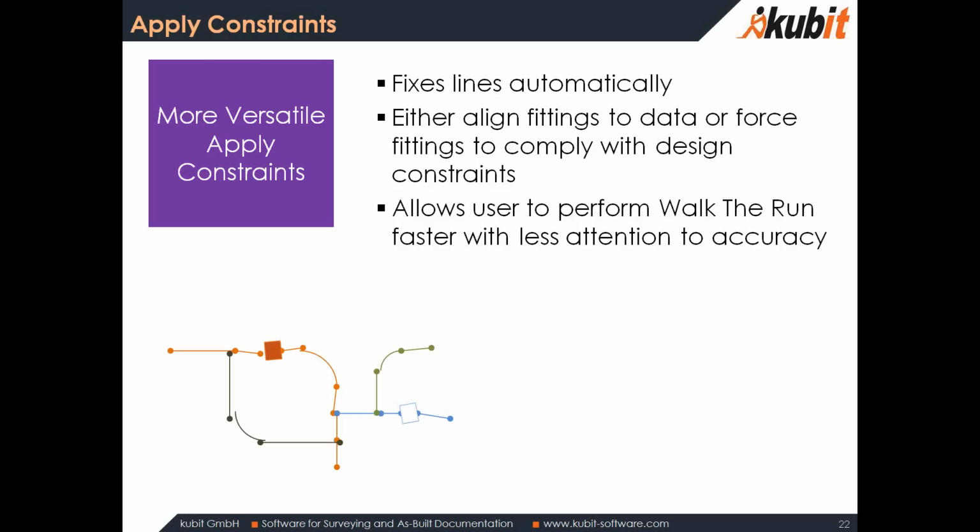And what we mean by that is, in the real world, fittings are going to be slightly off of their catalog version. They're not going to be exactly 90 degrees. It could be 89.97 or something like that. But in order to take these into your piping packages, they expect these fittings to be perfect. They're looking for design, not as-built.